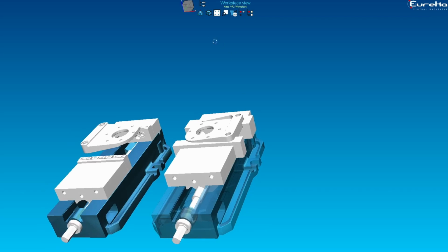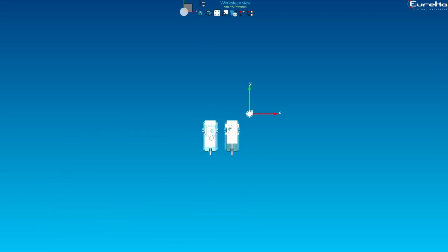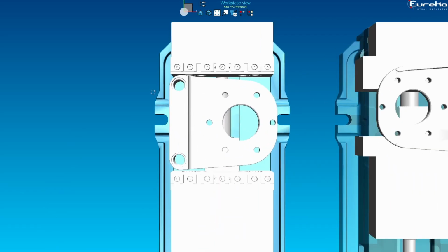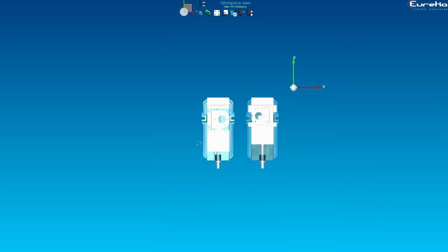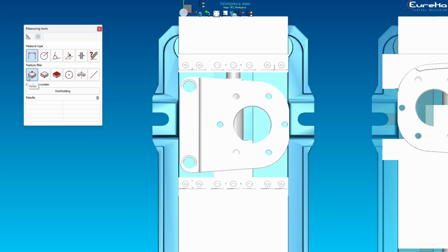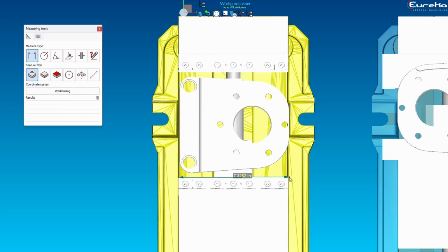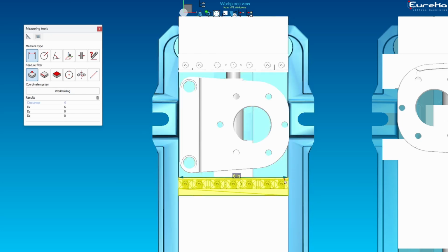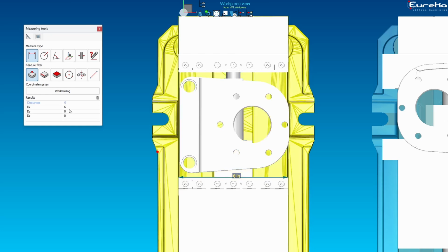Let's go to a top view in our workspace. To do that, click this top face on the view cube. And then let's zoom in on the part. I want to switch over to an orthographic view. So I'll click this button here and I'll zoom back in. Let's open the Measure tool. You can measure distance between vertices. Let's go to our selection mode and click two vertices, and we'll see the measurement is here in the workspace as well as here in the measure window.